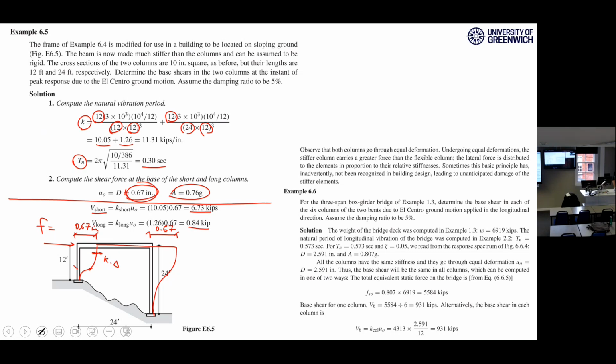And they don't realize that in the case of an earthquake, the external forces can go far differently into different columns. And they can break this column at the first instance. I think sometimes I've seen it, so sometimes what they do is they might have the same column section, but they rotate the column around, change the direction. That's another problem. That's another problem.